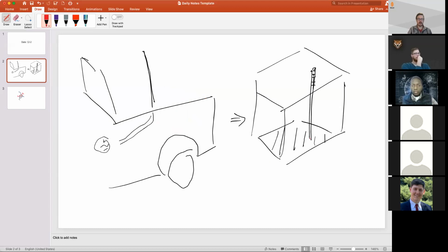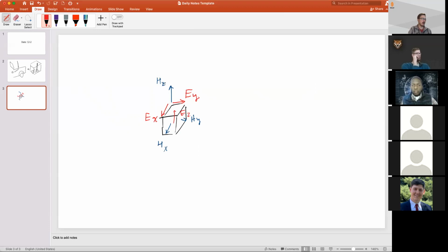And for each time step, right, if you had a source, if this was the source right down here, like if this antenna was connected to the source, we would say that we could start the excitation of this whole system from this source. So we say at time 0, it goes from nothing to being excited. And then we could gradually expand out from this central excitation point, what's happening at each different corner of this. All right, so then you could calculate all of the E and H field at each corner here.